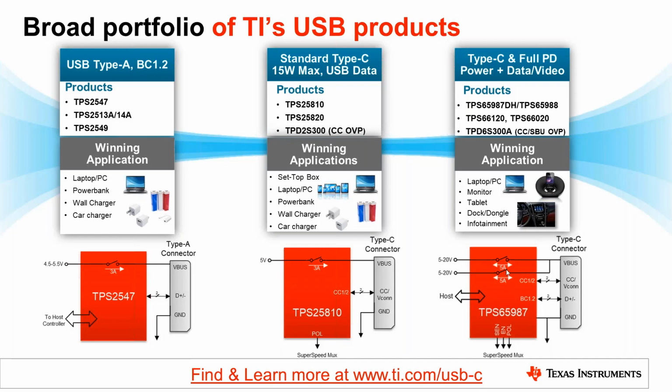This is important for Type C and power delivery systems since you can do both sourcing and sinking of power on that same port. However, typically, you don't want that power to go or come from the same places. An example of this would be if you're using this first power path to source power, you would connect this line here to your DC to DC supply, which generates your sourcing voltage. However, if you're sinking, you can use this second power path here and connect this line here to your battery charger or your other system rail where you want your sinking power to go.